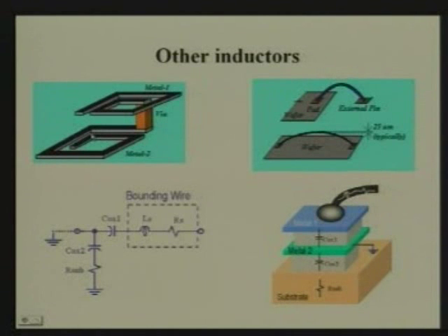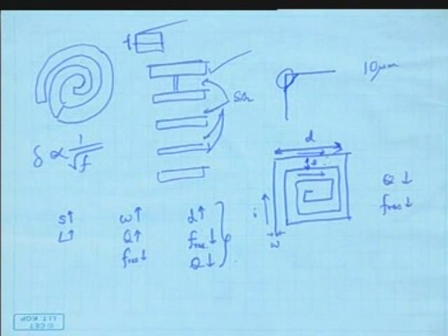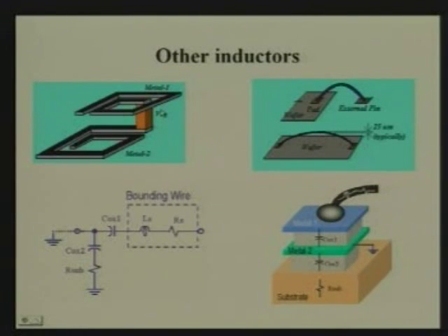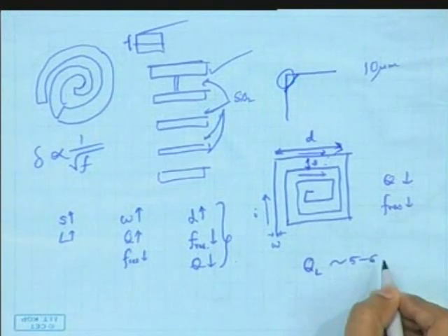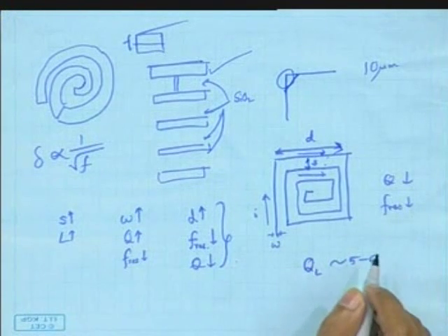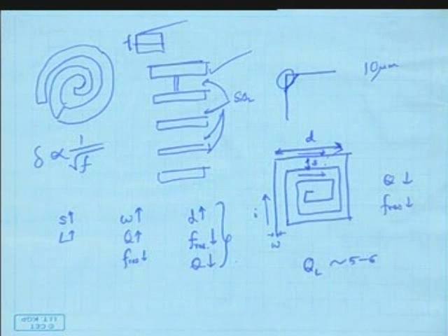What about the capacitance? Yes, so within two layers we will have capacitance that will degrade the resonant frequency again. Now these inductors on chip in general have a quality factor of 5 to 6, which is very low. So on chip QL is around 5 to 6 compared to around 30 for the capacitance. Now suppose in an application you need a very high quality inductance.